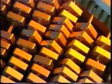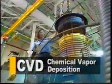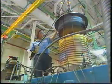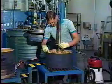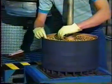Two processes are commonly used: CVD, or chemical vapor deposition, and PVD, physical vapor deposition. In the CVD process, inserts are loaded onto tungsten rods in graphite trays and are heated to 1900 degrees Fahrenheit in a hydrogen atmosphere.